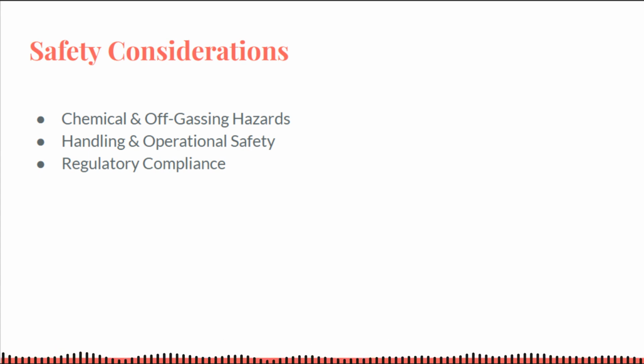Residential pools don't have specific ozone limits in most areas, but commercial codes often require that any ozone in the pool water be under 0.1 parts per million at the return, which is usually the case naturally. It's wise to follow similar principles at home. Ensure the ozone output is tuned properly so no strong ozone smell is detectable at the pool. When used as directed, ozone and AOP systems are safe enhancements that meet relevant standards. Look for NSF/ANSI 50 certification, indicating the unit was tested for disinfection efficacy and safe operation.